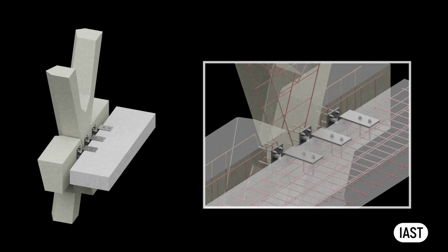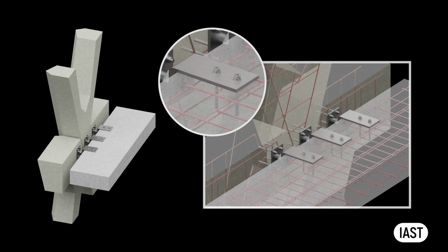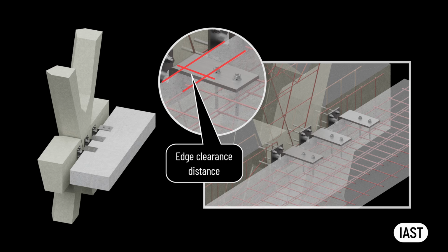Concrete is a brittle material. This should be considered when selecting fixings. All fixings to new or existing concrete should be pull-out tested. Another consideration when designing the connections is the location of the fixings relative to the existing rebars within the concrete panels and the distance between the edges of the concrete and the center of the fixings, commonly referred to as edge clearance distances. These parameters are crucial in the fixing selection process and when deciding on bracket configurations.